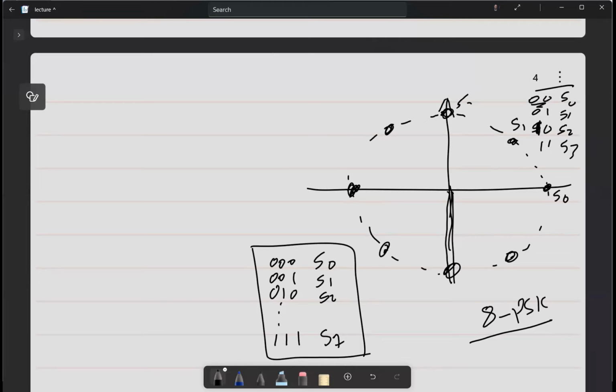but I would just like to show you how this probability density function could be applied here. So now when you send symbol 0, for example, due to the noise and multipath, you will never receive it in the same location. It will be shifted due to noise and due to interference. So when you send S0, you might receive it here, here, here, or here. Theoretically, you might receive it anywhere.